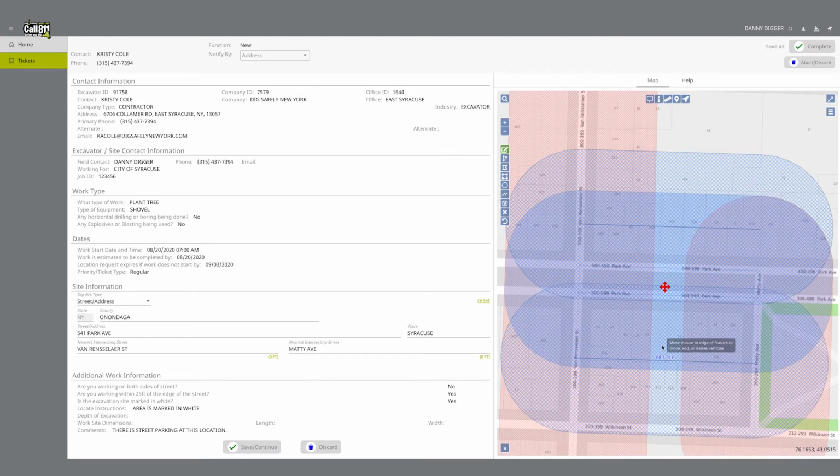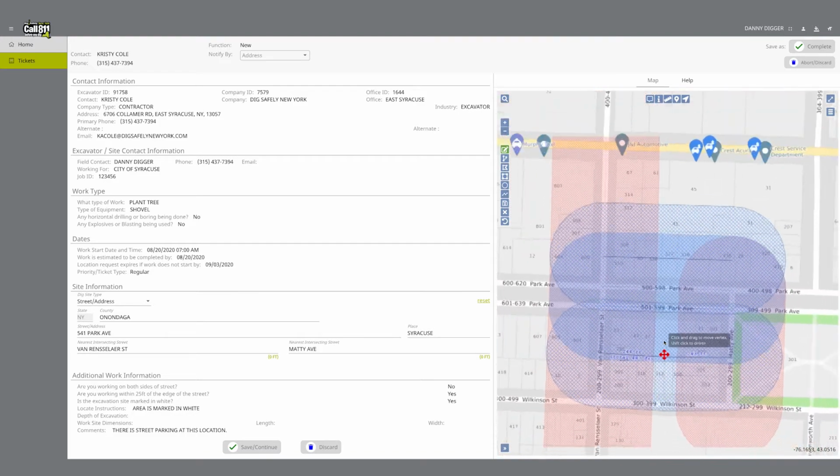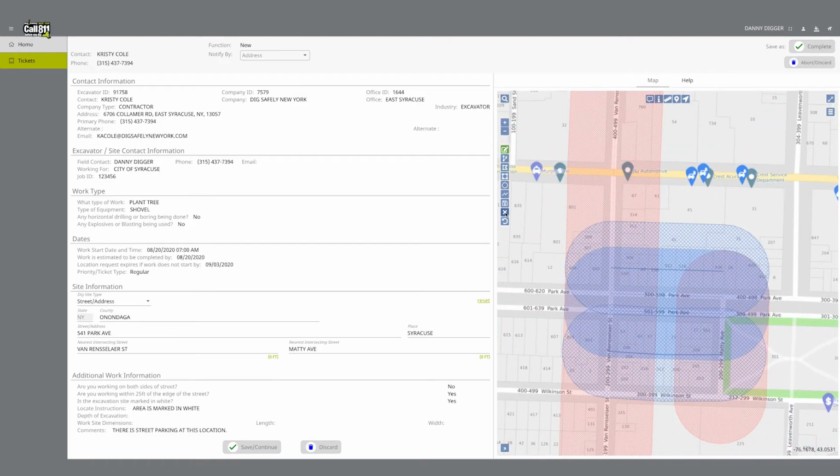By clicking within the now gridded dig site area, you can move the area entirely when you click, hold, and drag the area to your desired location. You can use the Cancel Discard button to go back to your original dig site. If at any time you need to erase a step you have taken while using the Edit Dig Site tool, click on the Undo button.